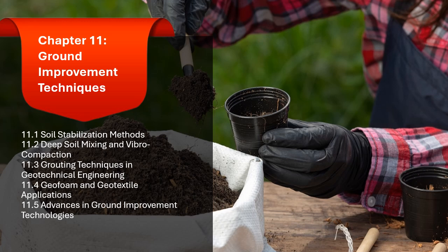3. Drainage and filtration. Geotextiles are highly active in drainage applications, where water flow needs to be controlled or directed. They act as a filter, allowing water to pass through while preventing soil particles from being carried away, thus maintaining the integrity of the soil structure. Example: geotextiles are used in the construction of French drains, stormwater management systems, and retaining walls to facilitate water drainage and prevent soil erosion.